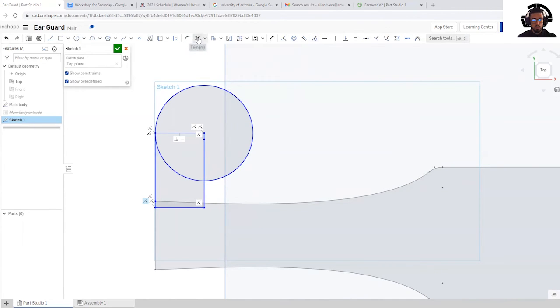I'm going to select the trim tool, and I'm going to start trimming lines. So I trim that top line, this side line, this line at this point, and now the reason why I saved this one for last was that it just created a point that intersected the circle, and made it so that I can trim this point without having any disruption amongst the circle. Say, for example, you were to have started with this, since there is no set point, you would be trimming the entire line.